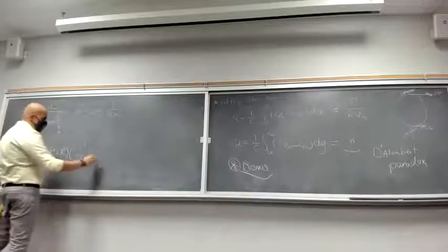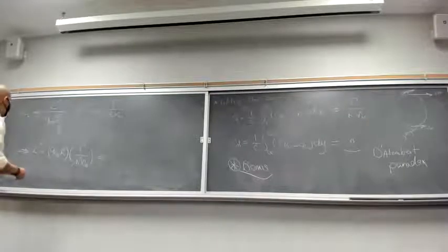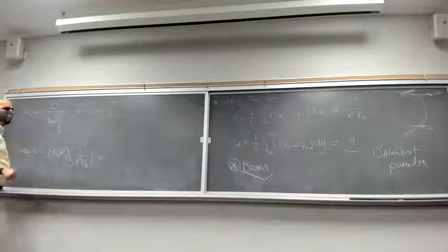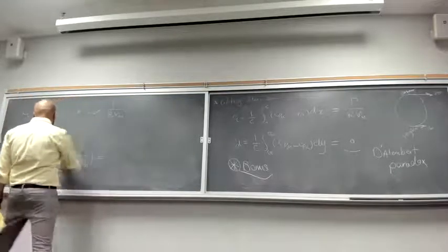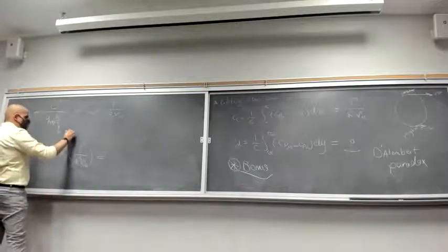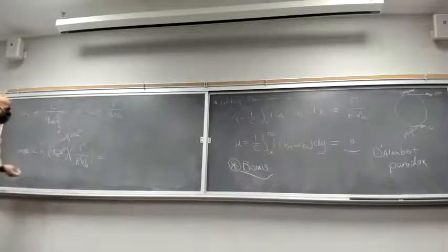These two will cancel each other out. Q infinity is your dynamic pressure, 1/2 rho V infinity squared, and this is actually 2R, because that's the diameter of your circle. Plug all of these in.